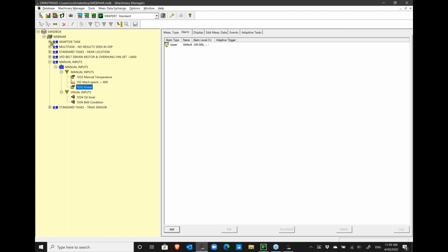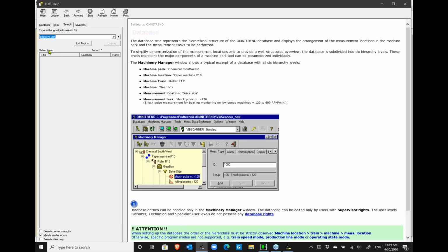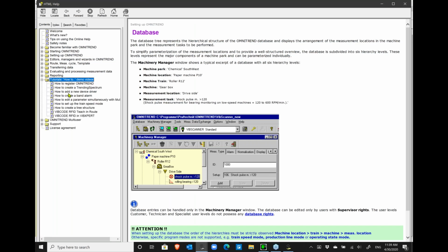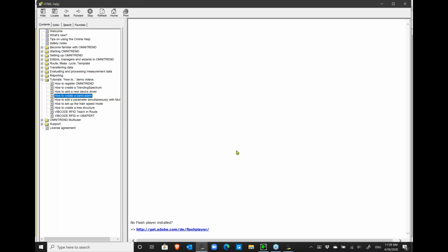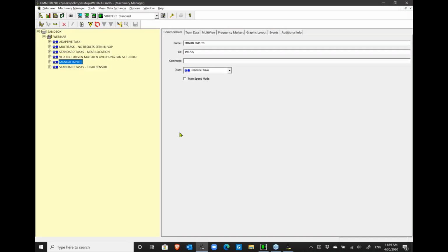There are lots of different options, and most of these are available as tutorial videos in the help files in the OMNITREND software itself. How to set that band alarm is one that we get asked about quite often, and I always teach my classes and show them how to get to it in the help files. We open the help file up, we go to the contents, we go to the tutorials, and there is how to create a band alarm as a tutorial video. Okay, so close the help file. So easy to find if you need that information.